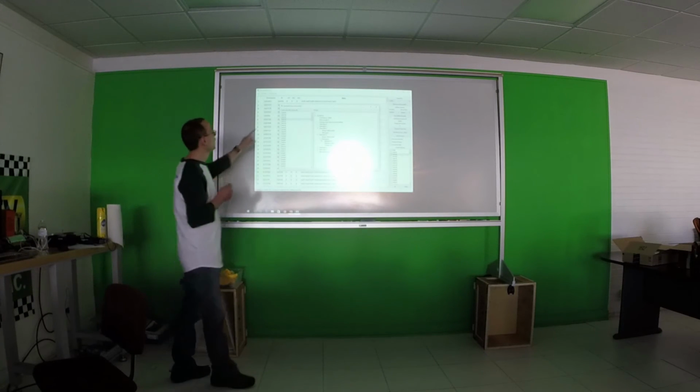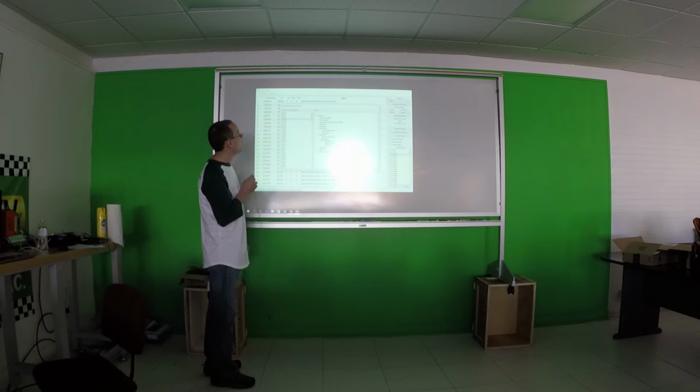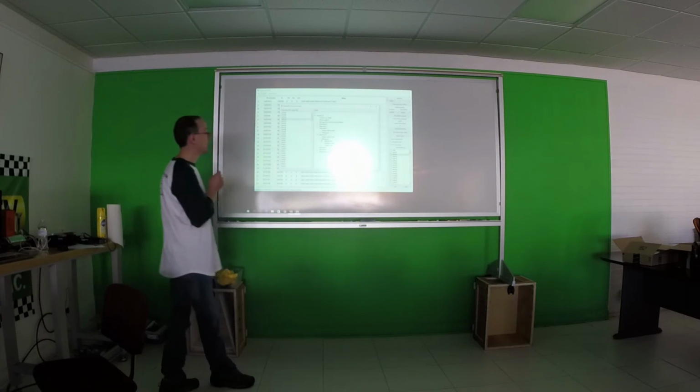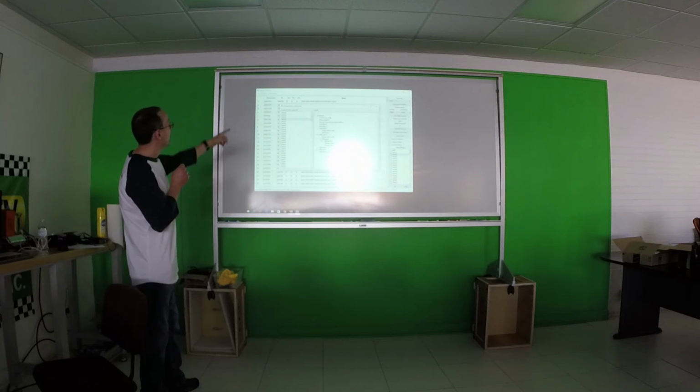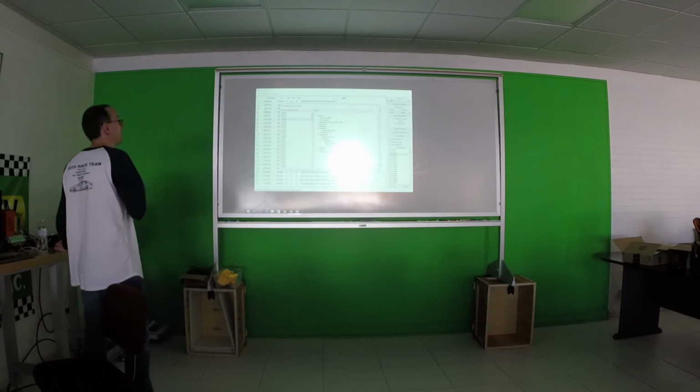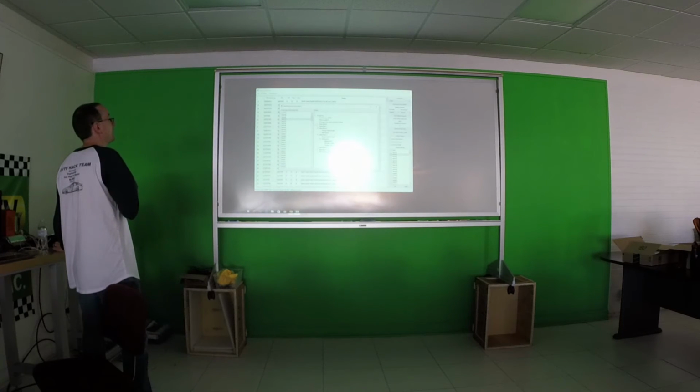As Jack covered, lower IDs have more precedence on the bus. So when you see inverter messages, and the Tesla is no exception, the inverter messages on a Tesla are 200 and 100 messages. They're fairly low in the ID, so you know those messages are very likely to get sent. It's kind of off the list because it's in E, but there's an ID of just E that's on the bus here.